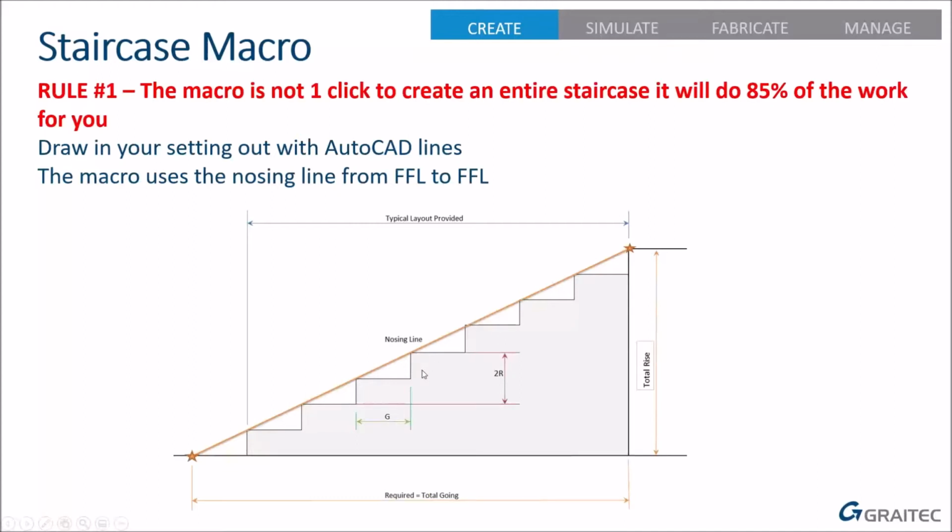So instead of using just the angle for a stair, most building regulations use a formula based on the rise and the going, and that's twice the rise plus the going, or 2R plus G, and the total has to be a certain number within a certain range, depending on what type of stair it is, what type of building it is, how often it's going to be used, and so on. So the macro in Advanced Steel is built around this 2R plus G formula as well.